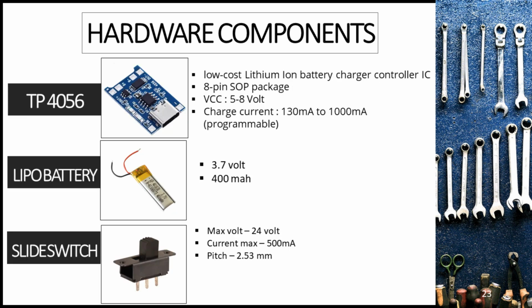And next, TP4056. It is a low cost lithium ion battery charger controller IC, and the VCC is around 5 to 8 volt. Next, LiPo battery, the voltage is around 3.7 volt and 400 mAh. Next, slide switch, the maximum voltage around 24 volt and the maximum current around 500 milliampere.